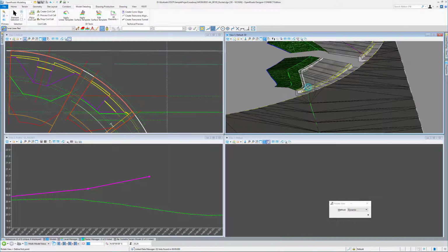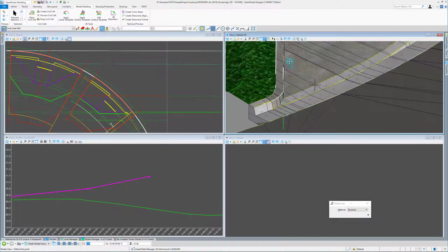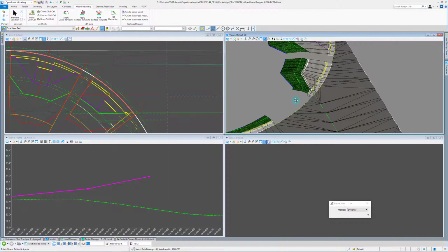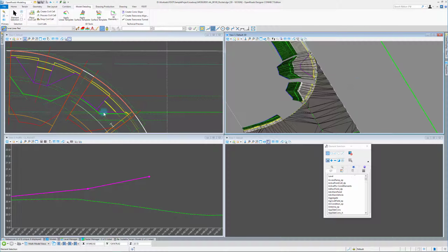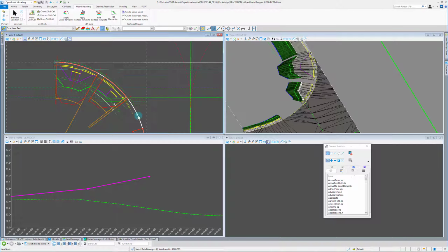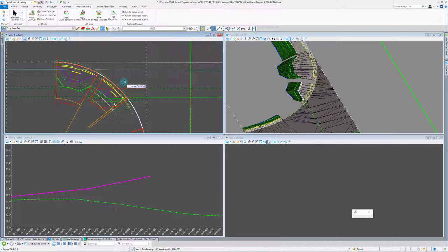Curb comes down, we got drop curb. Sidewalk curb comes around, matches up with the regular F curb. Really nice. So now what we need to do is a little bit of cleanup to finish up this side. What I'm going to do is drop these civil cells. I don't really like keeping civil cells active in my files. It might be an old SS4 thing, but too many civil cells in your file really causes it to bog down, so I tend to drop them if I've placed them and they look correct.